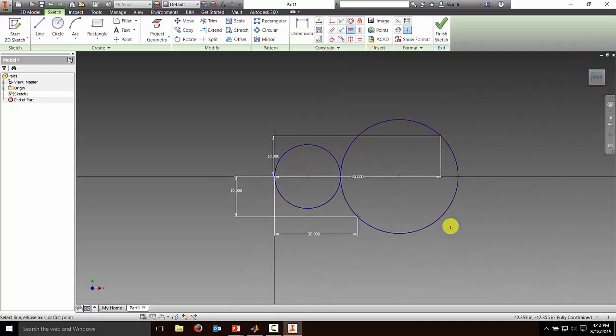And I need to make one more circle. I've got point 1, 2, and 3. I've connected circles between 1 and 2, and between 2 and 3. I just need one more circle that connects 1 and 3. So again, let's make a circle, and I'll again snap it to this point. Use the coincident tool and snap the circle to point 3, and the last one is horizontally. I'll make sure that the center is on the x-axis. So there's my Mohr's circle.